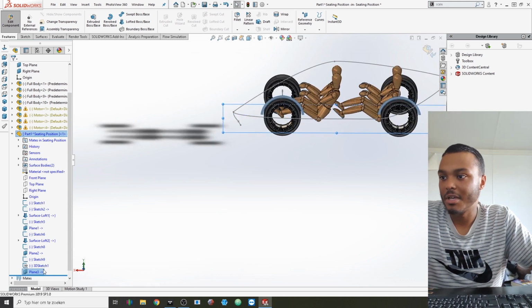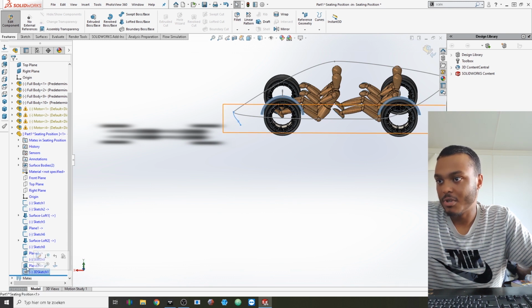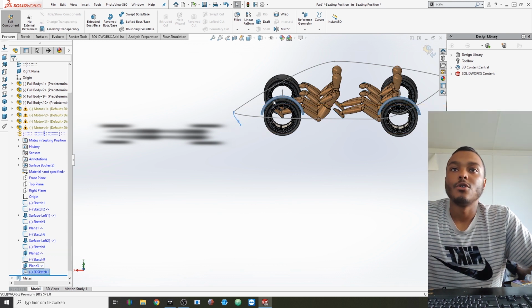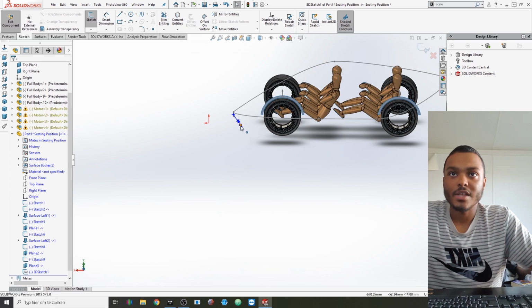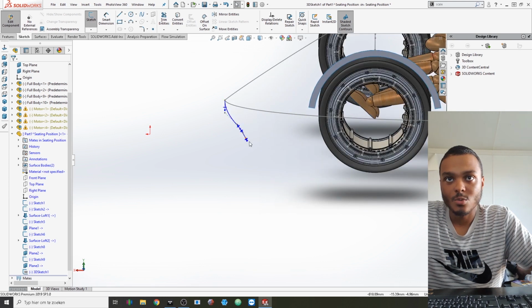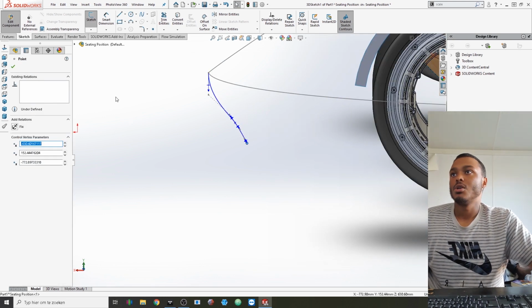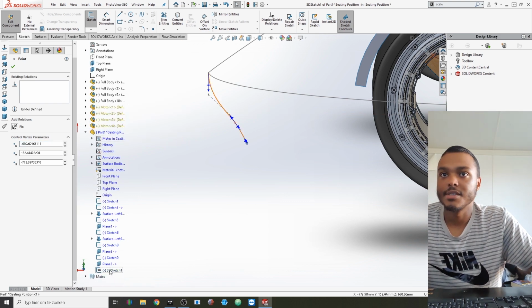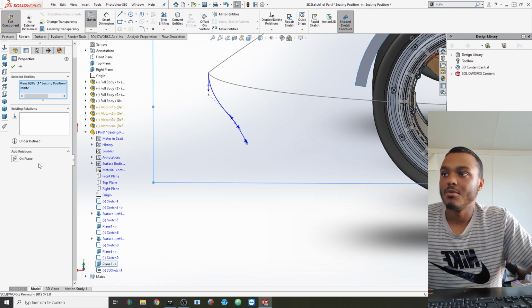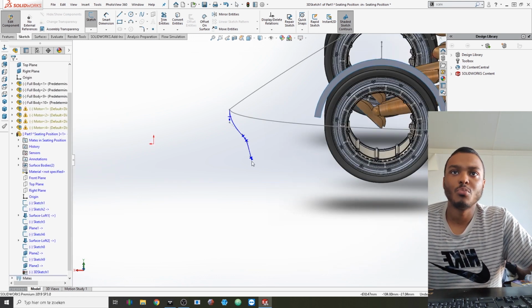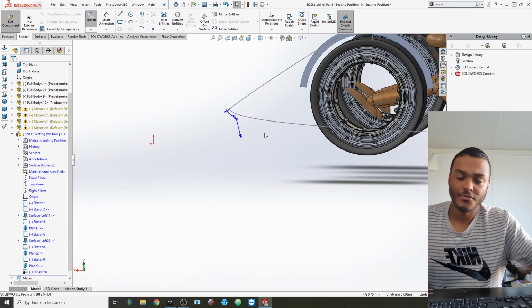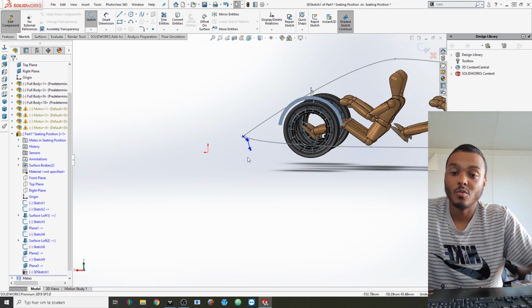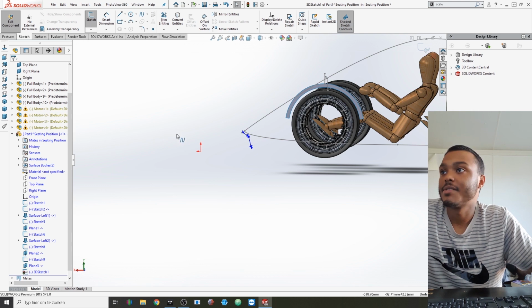And that is very handy to have, because if I can then drop it across that 3D sketch that we just made and go back to that sketch, I can select this point right here that I want to touch the floor, hold down my control button and then select this plane, and then we can select add on plane. So then you can see that that point will be attached to that point on the floor, and that will make your life for the whole build easier with attaching other lines to it and everything.